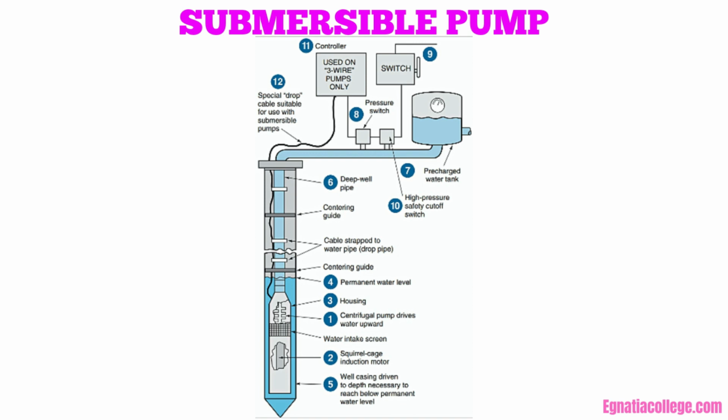Some water tanks have a pre-charged air chamber containing a vinyl bag that separates the air from the water. This assures that air is not absorbed by the water. The absorption of air causes a slow reduction of the water pressure, and, ultimately, the tank will fill completely with water with no room for the air. The use of a vinyl bag to hold the air ensures that the initial air charge is always maintained.